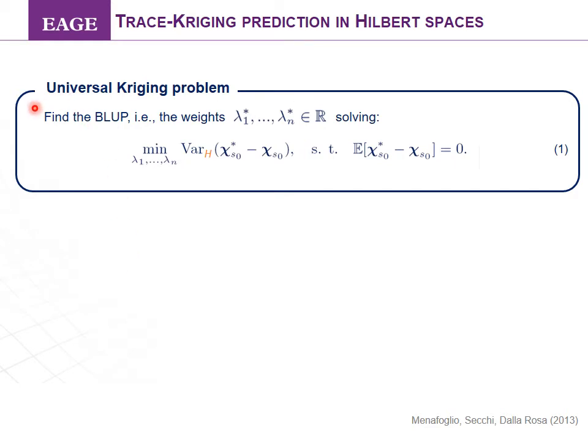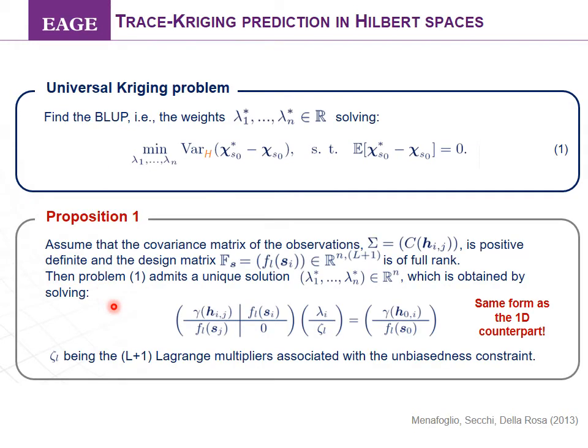So as you know, in the universal kriging problem, we will be minimizing the estimation variance, the average square difference between the estimator and the true unknown, under some unbiasedness condition. Without going too much into the details, this looks exactly like a universal kriging system. In a universal kriging system, we get the components related to a matrix. We have the weights here, Lagrange parameters there. We have a matrix, and this is a vector.